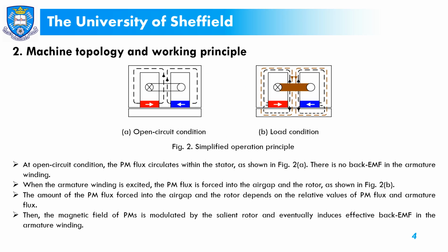To explain the working principle of stator slot PM machines, a simplified model is employed, as shown in Figure 2. At open circuit condition, the magnet flux circulates within the stator, and there is no back EMF.